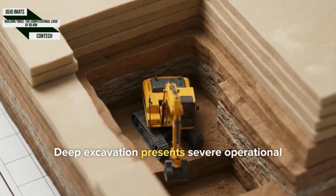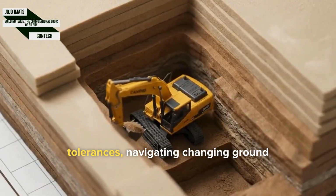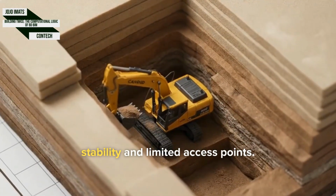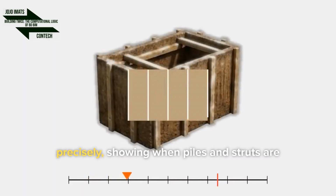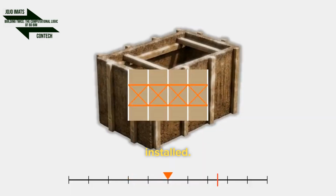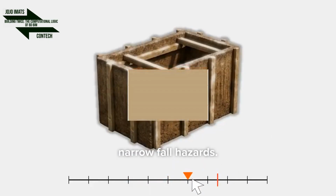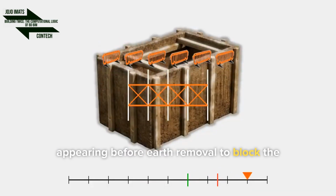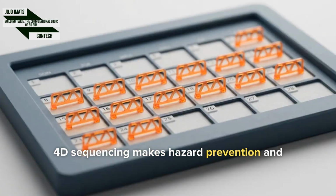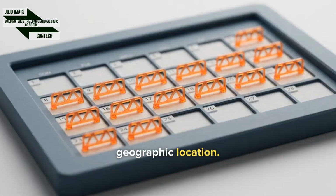Deep excavation presents severe operational risks. Heavy machinery must operate with tight tolerances, navigating changing ground stability and limited access points. Earth-retaining structures are sequenced precisely, showing when piles and struts are installed. Officers scrub this 4D timeline to pinpoint narrow fall hazards. A physical safety barrier is then scheduled, appearing before earth removal to block the hazard before it materializes. 4D sequencing makes hazard prevention an actionable, scheduled event rather than a static geographic location.